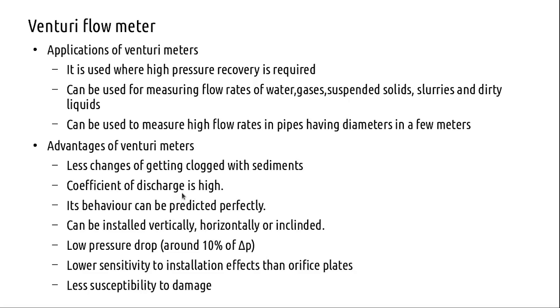All those things are there, and the pressure loss is much lesser than that of an orifice plate. Much lesser drop in pressure occurs in Venturi meters, say 10% loss of pressure downstream than the upstream case. In the orifice plate, around 40% loss in the pressure head happens.